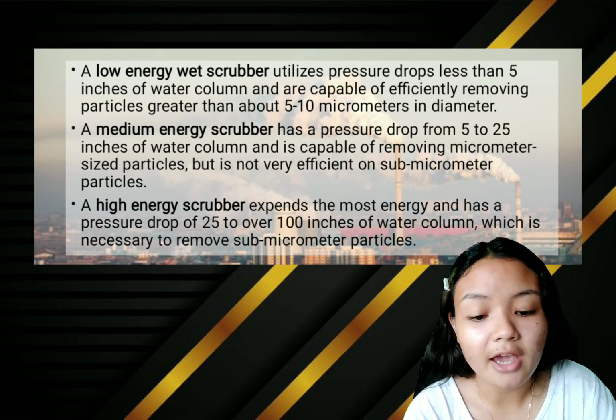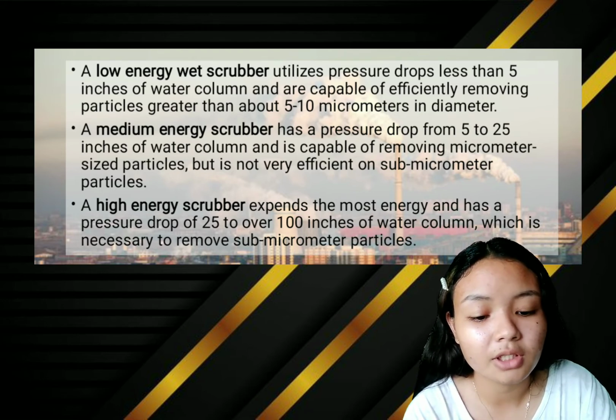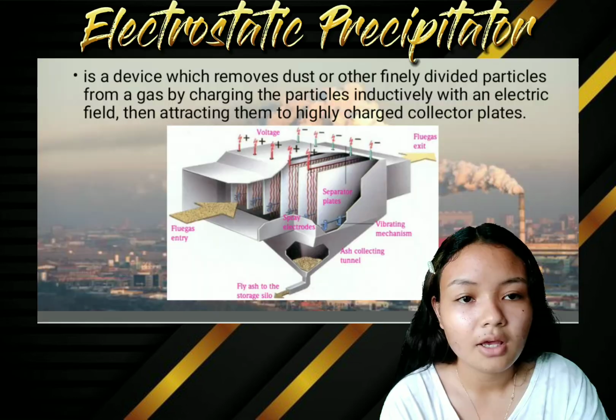Last is a high-energy scrubber. It expends the most energy and has a pressure drop of 25 to 100 inches of water column, which is necessary to remove sub-micrometer particles.